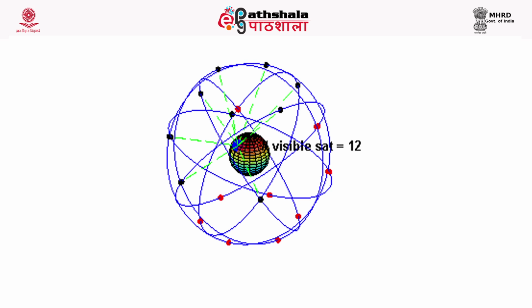So, when we have the red circles for all these satellites, the common areas of intersection between 2 satellites will reduce the error. Accordingly, when we include the third satellite also, the intersection point of all these 3 satellites will give you the absolute location of a place. This figure shows the visible satellites at a given blue dot, that is a receiver, at any point of time which keeps on changing.